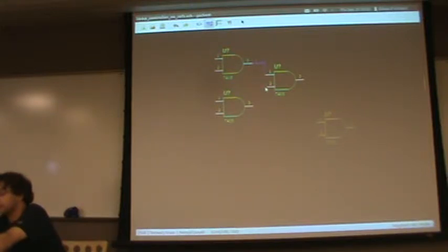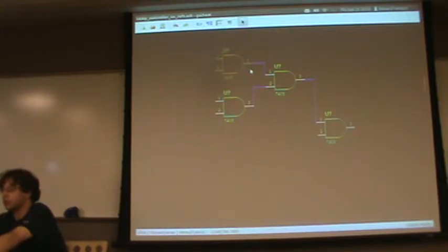Incidentally, if you're wiring and you right-click, it'll end the current wire and start a new one. So that's a right-click there. Okay. So now I've wired these together. Let's say I don't want to use 1/4 of 4 chips. I want to use 4/4 of 1 chip.